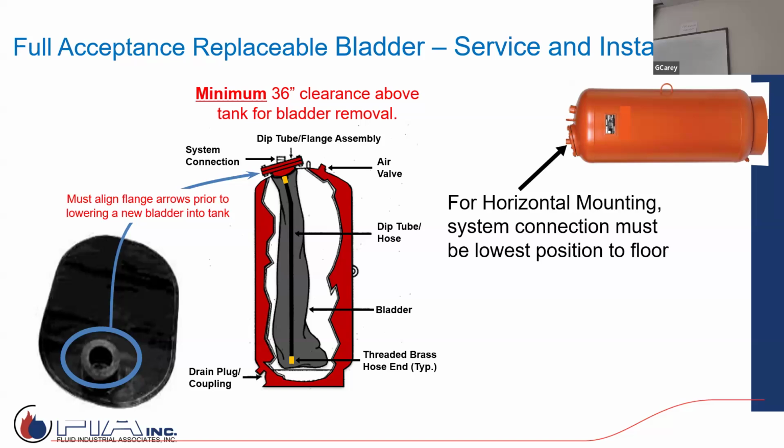So sometimes, and we'll get into it a little bit at the end, maybe one big tank can handle it. But maybe the real right answer is to specify two smaller tanks that can get in easily and not take up that much space in the mechanical room. And then down the road, from a serviceability standpoint, maybe it just makes more sense in labor and time. If something did happen, I take one of them out and replace it.